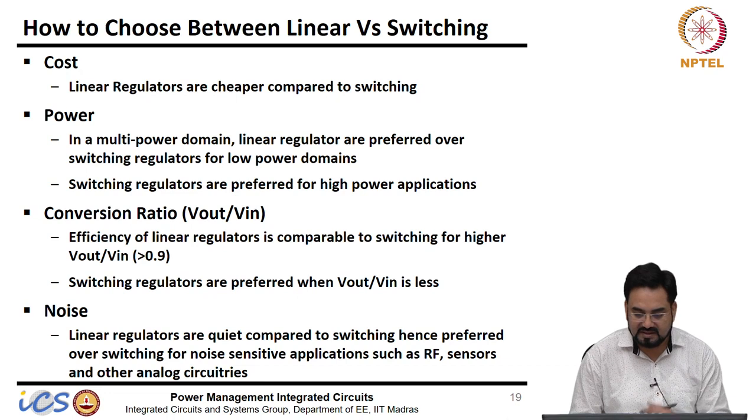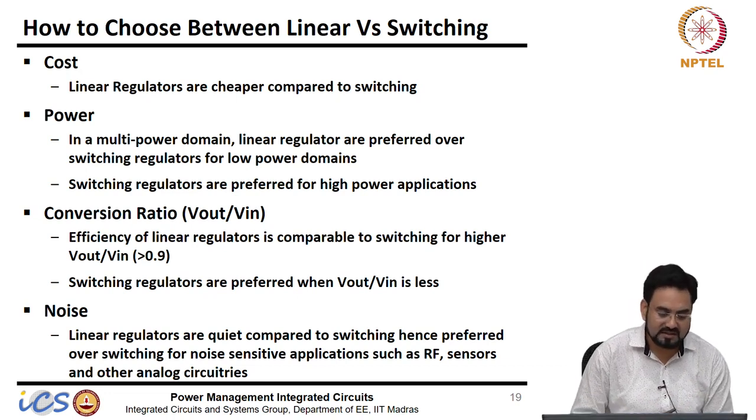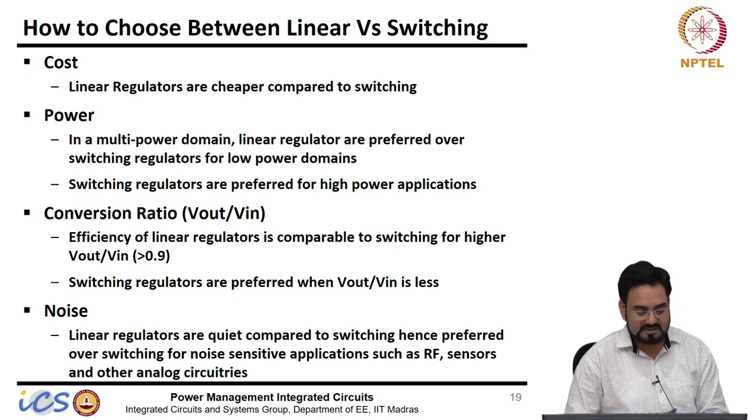Linear regulators are cheaper compared to switching, mainly because they don't require an inductor, and inductors are costlier compared to capacitors.